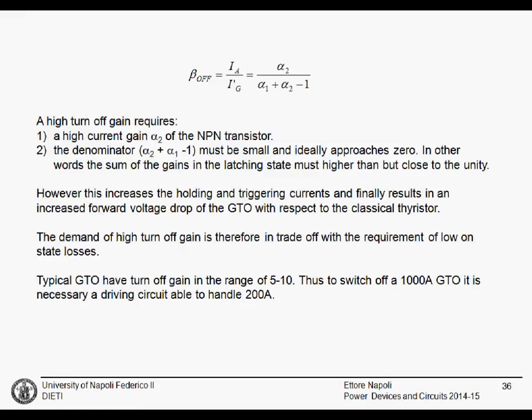You are asking for an added feature, that is the switch-off capability. You are paying for this with something higher, the on-state power or voltage drop, for example. There is obviously a trade-off between on-state voltage drop and turn-off gain.